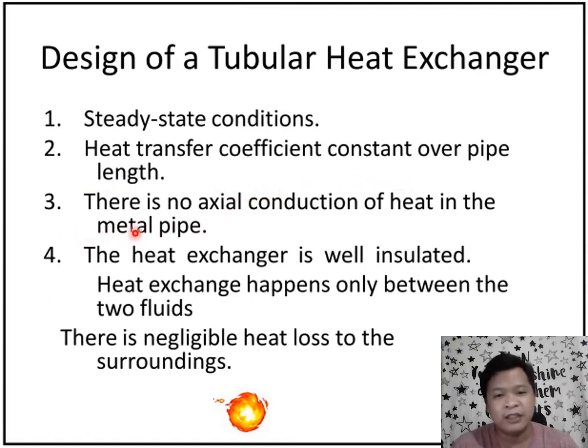Next is that the heat exchanger is well insulated such that heat exchange happens only between the two fluids. In reality, that is not the case. However, to simplify the problems, you have to assume the negligibility of other heat exchanges unless otherwise mentioned. Also, that there is negligible heat loss to the surroundings. So, of course, these assumptions are ideal, but they do make our calculations easier.